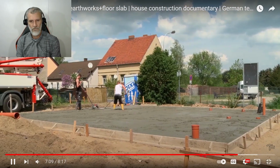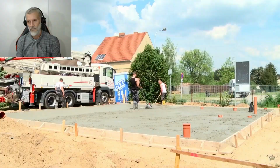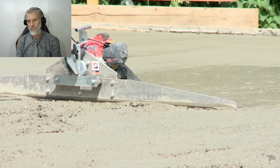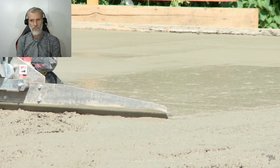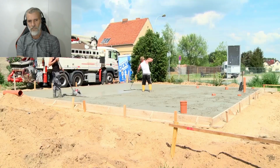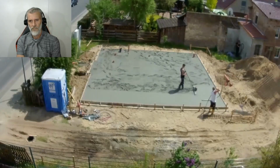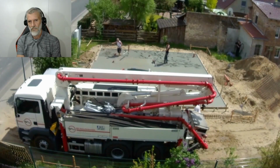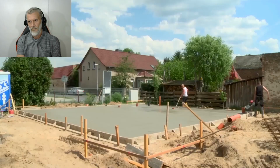The surface vibrator conducts high-frequency vibrations into the concrete. This increases the flowability of the fresh concrete. Air pockets rise to the surface and can leave. This is the way to give the concrete its perfect, dense consistency. Smooth with the peel-off surface. Done.